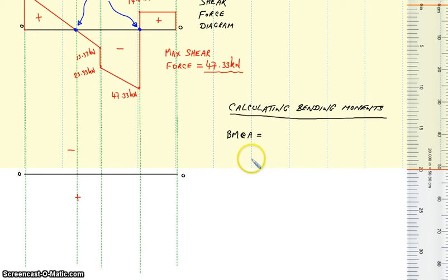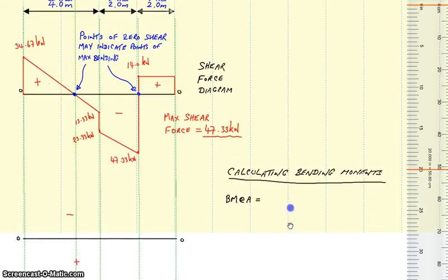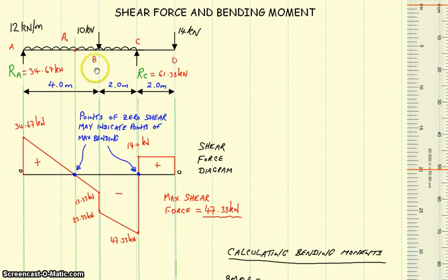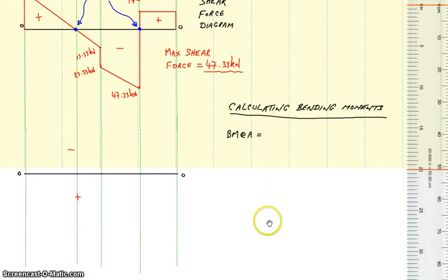So obviously, if you are in a position there, and I'll just drag this back up, to look at our diagram, if we're considering point A, then we can ignore everything to the right of A, which is all of the beam, and consider only to the left, which is absolutely nothing. So obviously, then we should realize very quickly that we couldn't possibly have any moments, and therefore the bending moment at A will be 0.